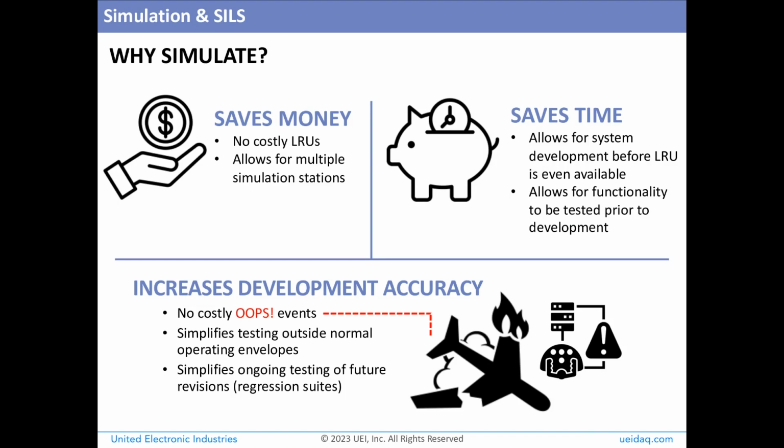Well, first of all, it saves money. If the controller is not complete or if it is expensive, why not simulate it? It is also easier to duplicate a simulated sensor or controller than a real one. Perhaps only a few were manufactured initially on the first run. It also saves time. Many teams can work in parallel. The functionality can be verified before it is actually put on a PCB board. It also increases accuracy. You can simulate failure modes without the actual failure feedback.